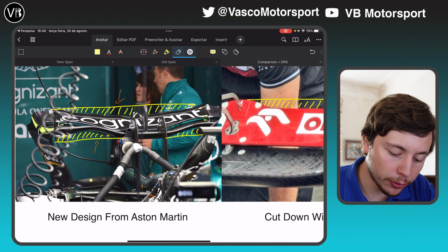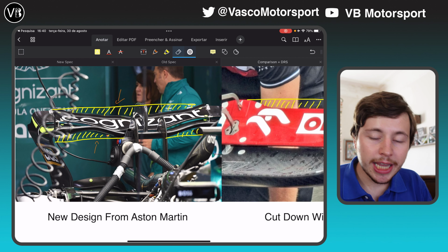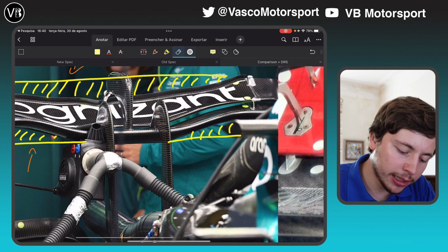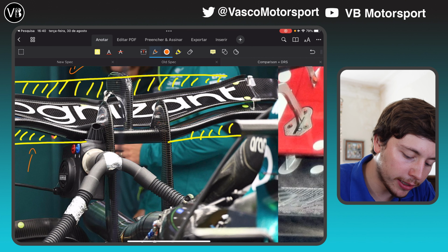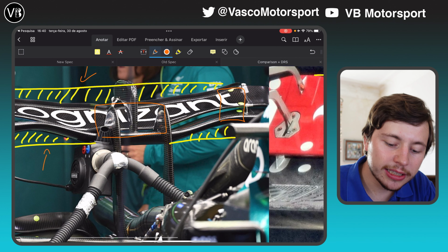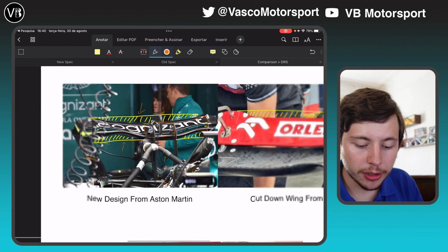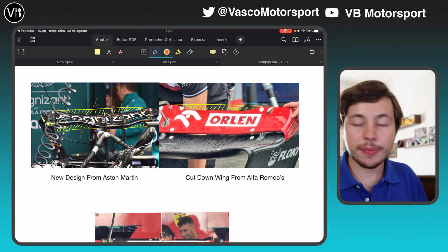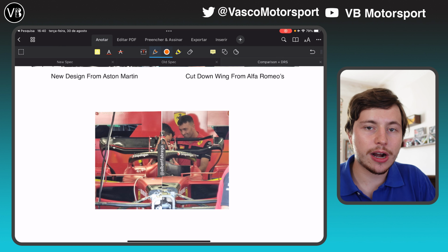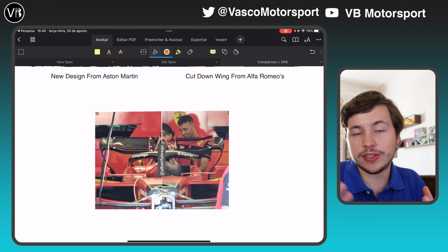Whereas with a wing with so little downforce as this, the difference between DRS open and DRS closed is going to be pretty much negligible in all aspects of the rear wing, with the exception of this middle part where the wing is still at its thickest. But basically in these points right here, the difference between DRS open and DRS closed is pretty much negligible. So the effect these rear wings are basically having is the same as having the DRS open through the entire lap. This is what teams want at Monza, because it's a circuit where the straights are the name of the game.